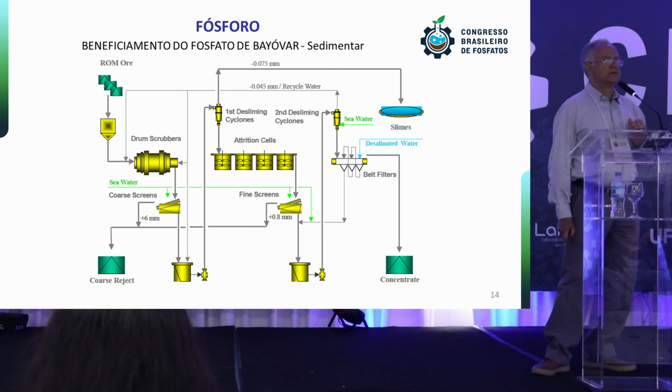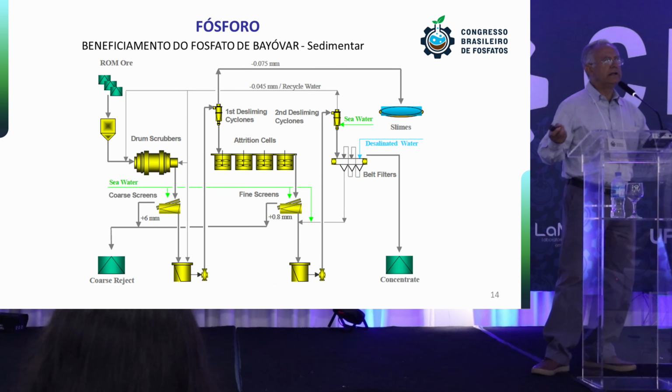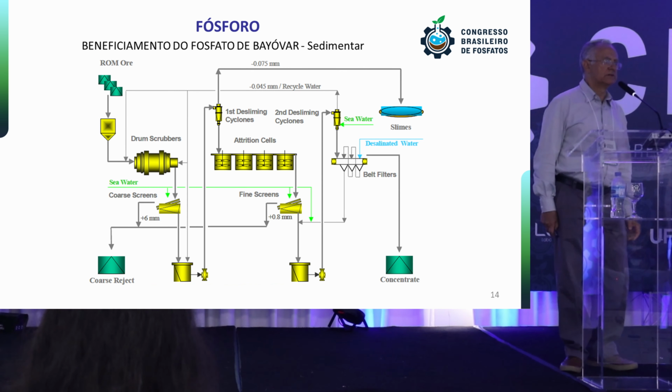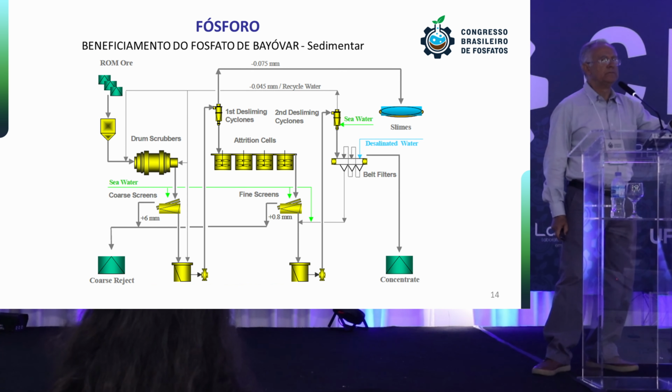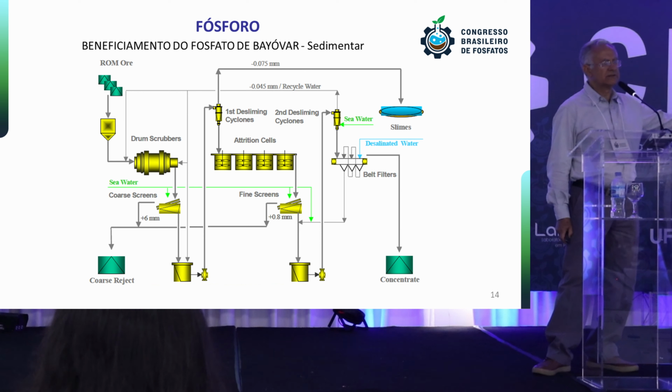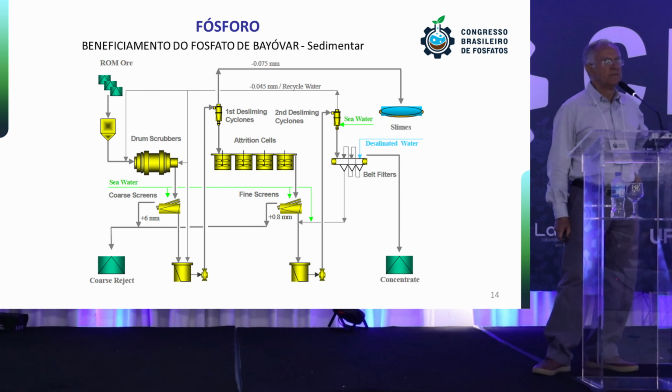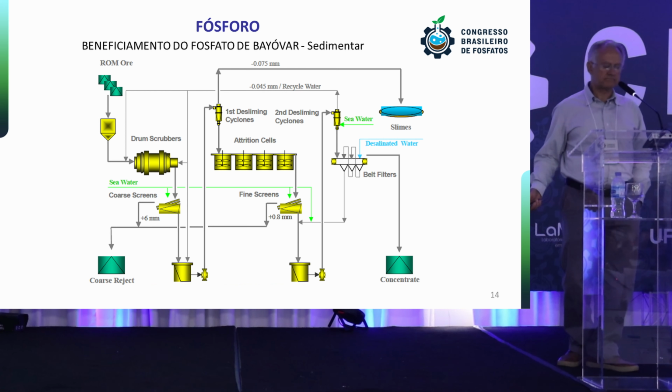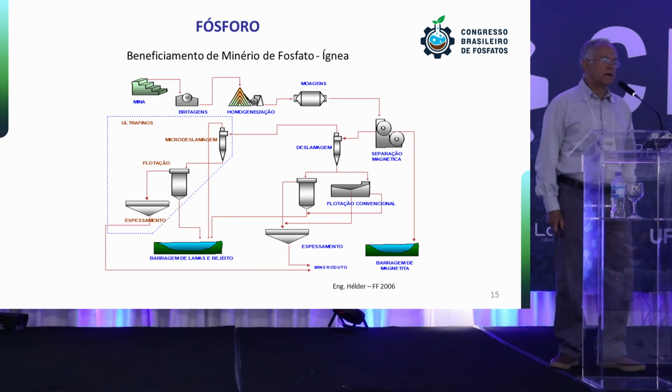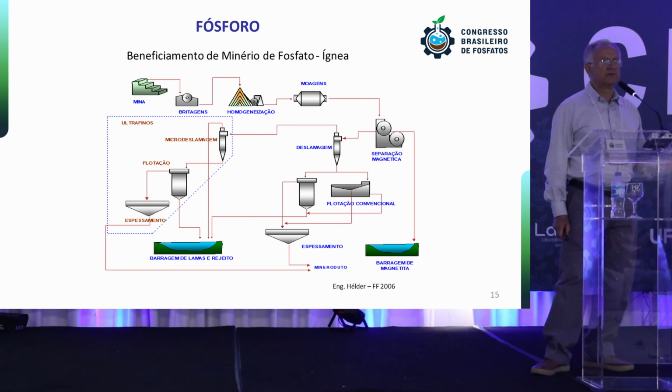So after the scrubbing, then de-sludging, it goes to filtration, where you use desalinized water to bring down the content of chlorine. And still, you have this liquid in the interface of the particles. When it leaves the beneficiation process it is around 1300 to 1400 ppm of chlorine, and after the washing it is 700 ppm of chlorine. This is the traditional process for beneficiation of phosphate ore.